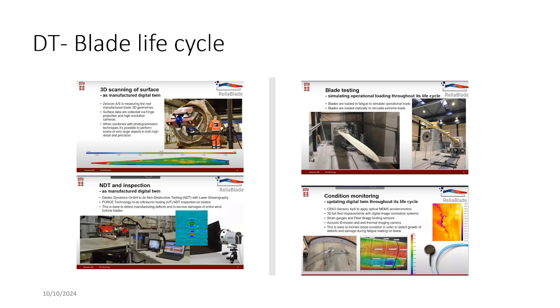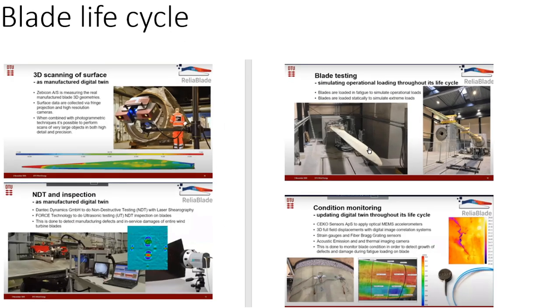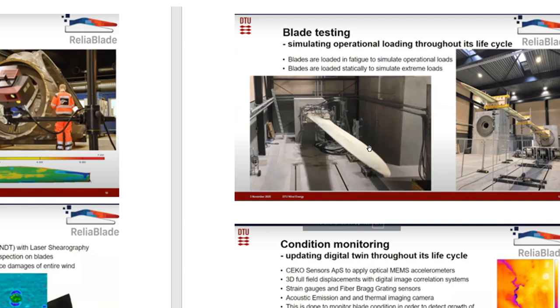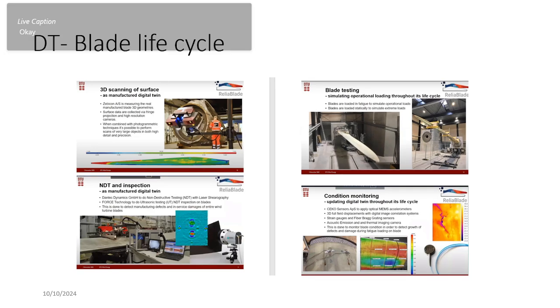So in a dynamic situation in a wind turbine, most of the parts, including tower, blade, and foundation rods, all of them will go through cyclic, alternate tension-compression reversal due to fluctuating loads. So that is called fatigue. And that has to be tested by blade testing, by oscillating the blade in different frequencies. So all those things are required.